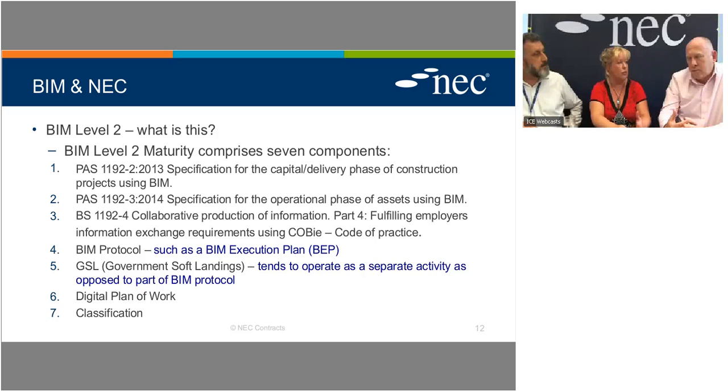So it's giving you a standard information and structure protocol, basically like a BIM programme to work through. It's not a form, it's a set of rules in which we will engage and use BIM on this particular project: who does what, when, how, where, with what data. It's a bit like a project execution plan. So you need definition of that early in the project. Yes, it really needs to start right at the front end. One of the first things that should happen through the pre-construction phase is the development of the BIM execution plan.